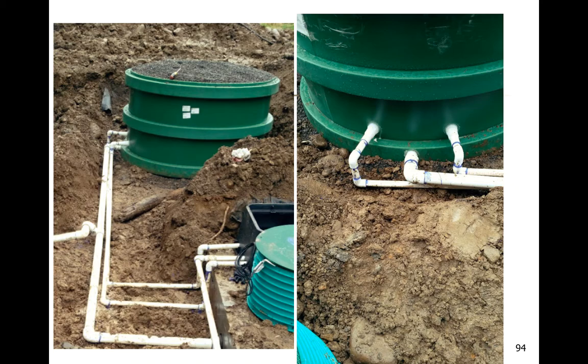You can see we've done the same thing on the left picture coming out of our headworks, where we'll elbow down to the trench bottom so that the piping is actually resting on somewhat bearing soil, so that when we do backfill, we don't have pipes suspended in midair. If for some reason you have to come straight out of the basin to get down to the tanks, use not just one elbow but two elbows. Again, the first elbow will go horizontal, the next elbow will adjust for the angle of going down slope down the trench.